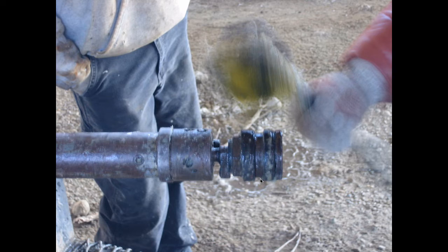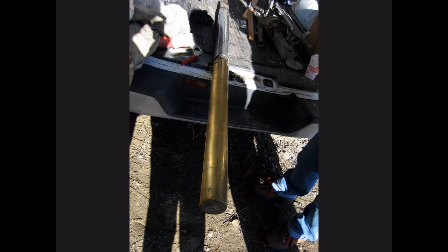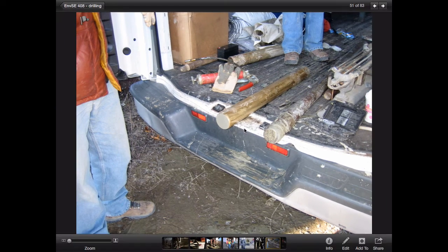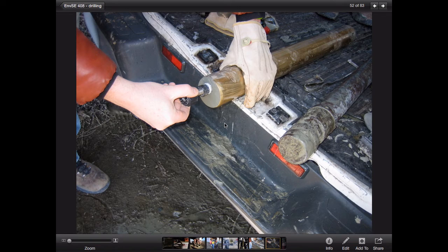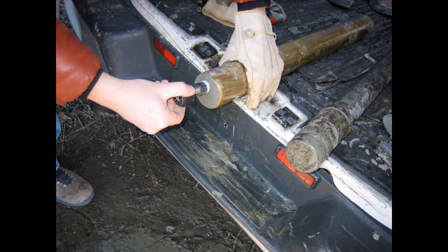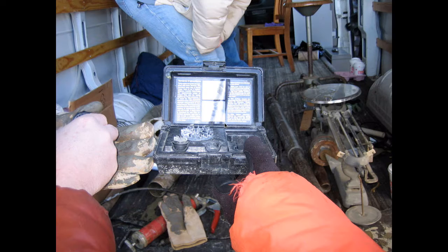That's people deliberating over the piston. That's the piston. That's the assembly. That's a sample that's come up. So this now is a tube. There's 18 inches probably of sample in this at the top. This is the retracted piston. Nice clean end at the bottom of this. You can do some experiments with it. You can twist a Torvane in it to be able to measure the strength, which allows you to classify the clay, for instance.